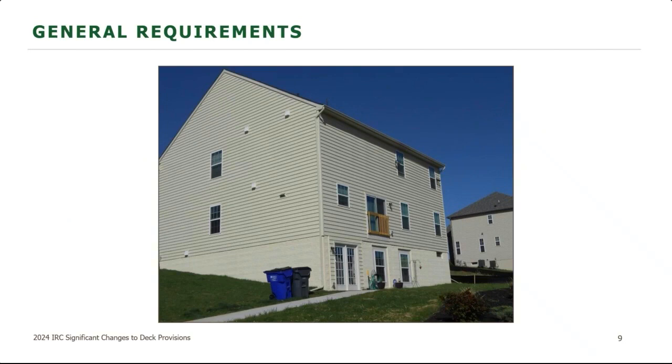However, if those doors from the walkout basement are a required exit and the deck above needs a post or a stair that comes down and blocks them, well, then the existing house is now less compliant with the code because that required exit door is blocked.